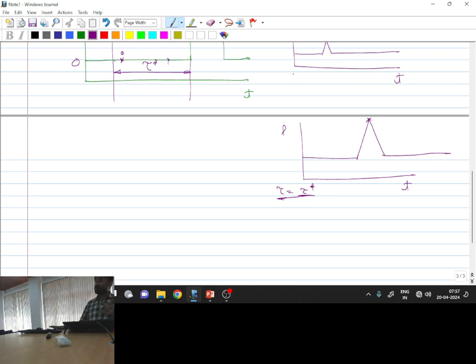Now how can this cross correlation data be utilized for measurement of velocity? So what you can do is, say you have a pipe, in this pipe you have a bubble. You will be giving one optical signal from here, you have some detector over here, then again a signal and then a detector here. So what will be happening? Say at some time t1 the bubble is at this point, so you will be getting the value of the signal something like this.